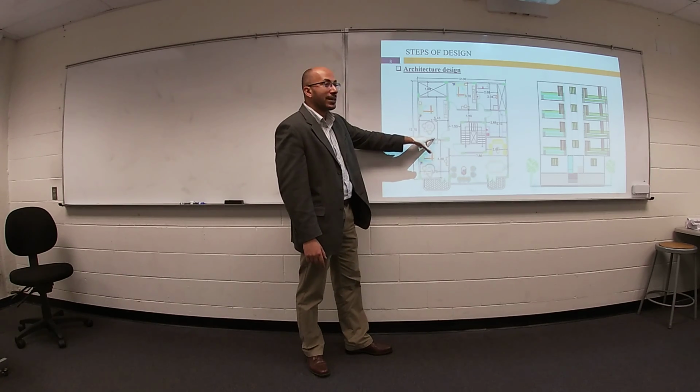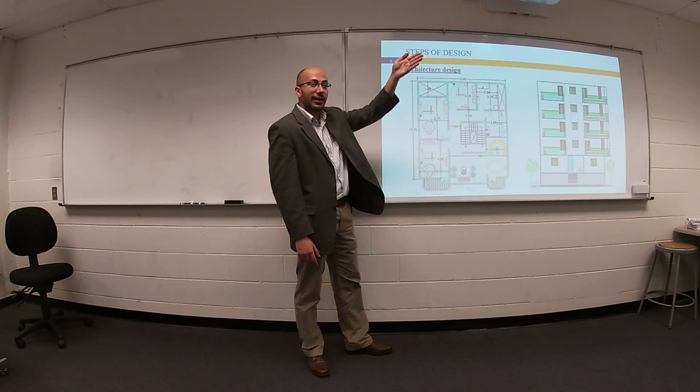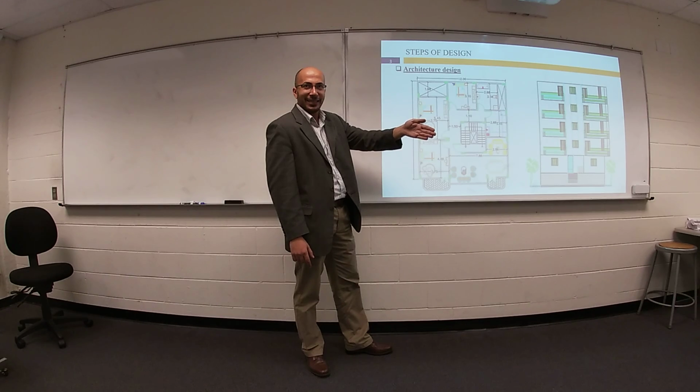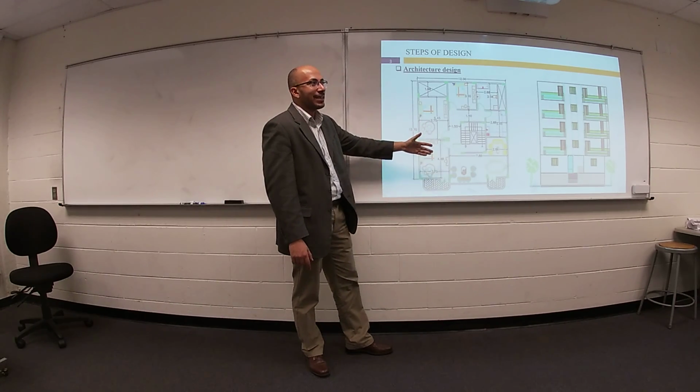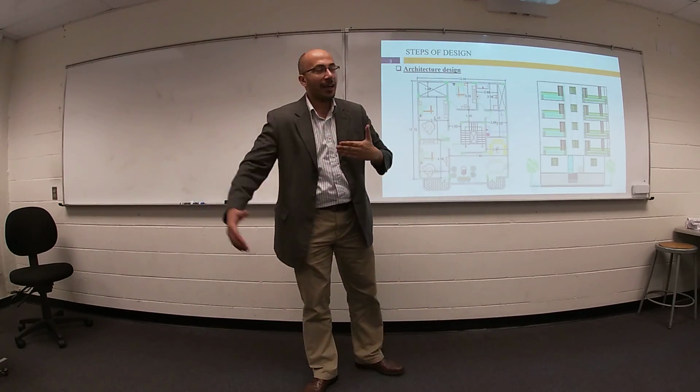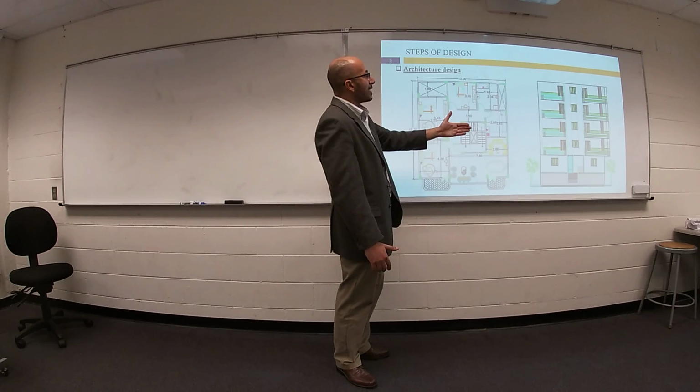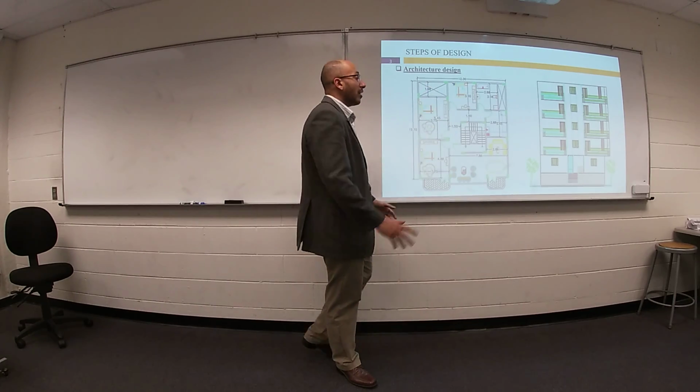This line, not a beam. This line is a wall. You know what I mean? This plan called architectural plan can tell me where is the wall of each room. Cannot tell me where is the beam, where is the slab, all of this stuff. But